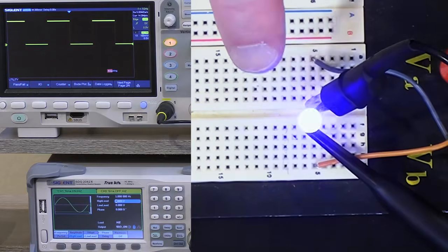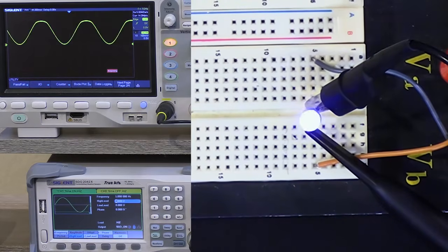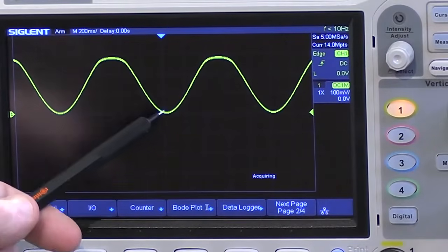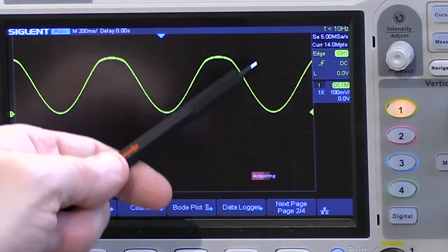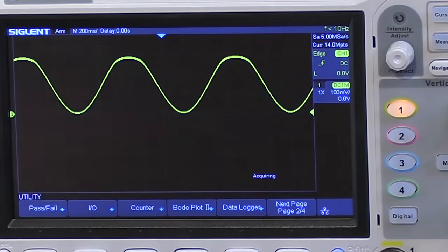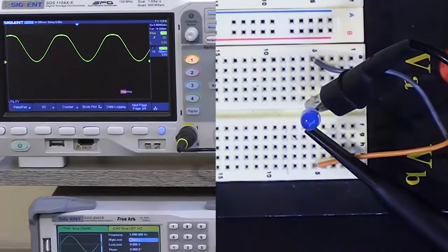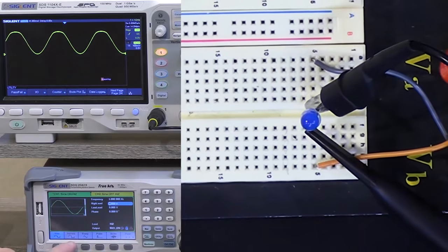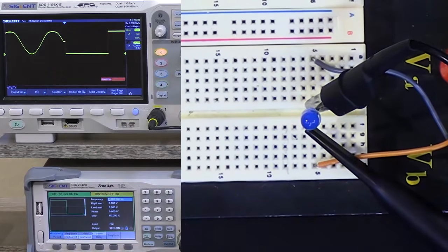Notice how it's still going on and off, but it's more fading in and out, because the voltage is going up gradually and then down to a low of 0, and then up gradually and down to a low of 0 gradually like that. So sine wave, more gradual. You can see the thing turn on a little bit easier. And then square pulse, of course, is just more of a flat on-off type of situation.